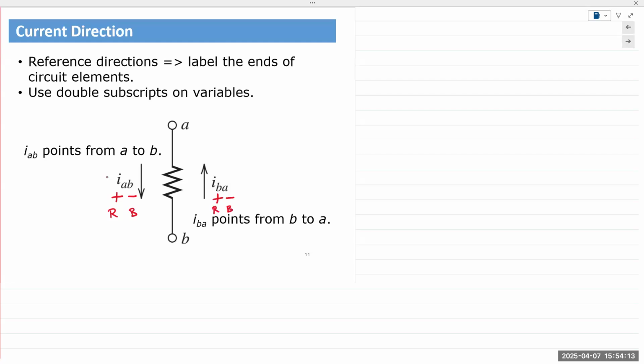Anyone have familiarity with measuring current using a meter? Okay. So you have to break the circuit, insert the meter in the middle, let the current pass through. Oftentimes, if you're in a rush, we neglect the direction of the current, either because we don't know or because we just need to find out. But if you want a positive value for current, then you look at your circuit, you inspect it, and determine which end is connected to the positive end of the power supply. That's the end where you would connect the red terminal of the meter. And the other terminal would go to the exit point.